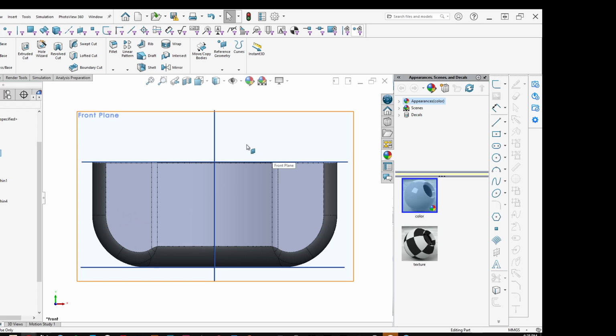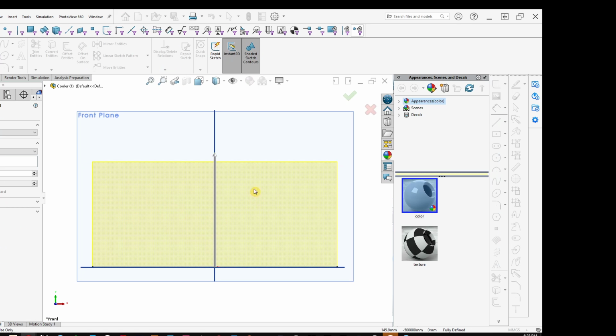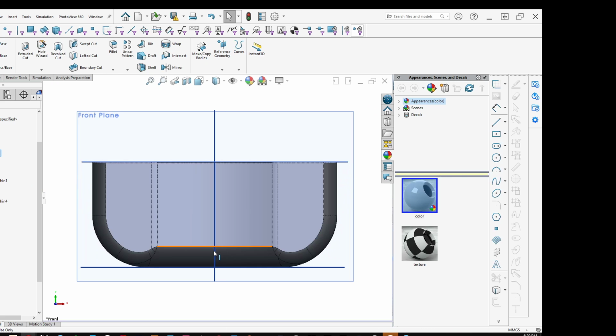Same as the top. Now, this is going to be a big thing too. Draft is actually really simple for a part like this. When you extrude it, if you know that you're going to need draft, it's as simple as clicking on the left on this button here, which is draft, and you've got 2 options. You can increase the draft, and it goes in the direction of your extrude. So you can increase it, and notice how it's going outward, or you can go inwards. Now, let me just exit out of that.